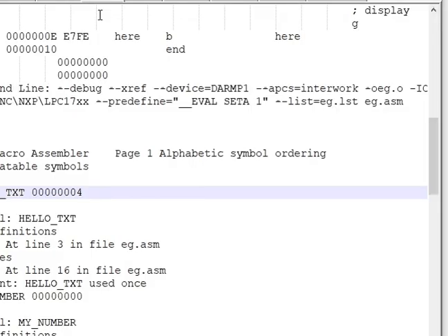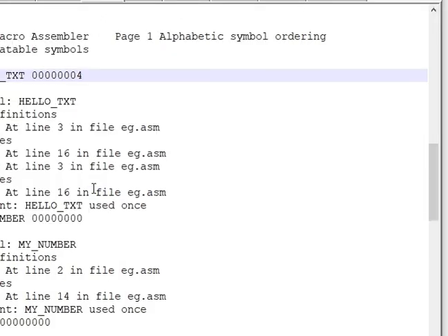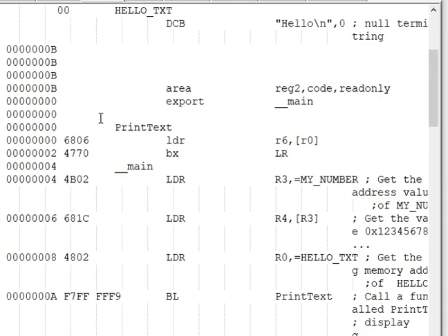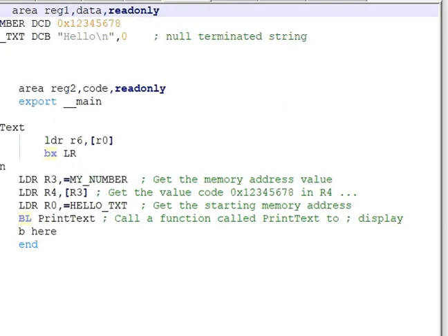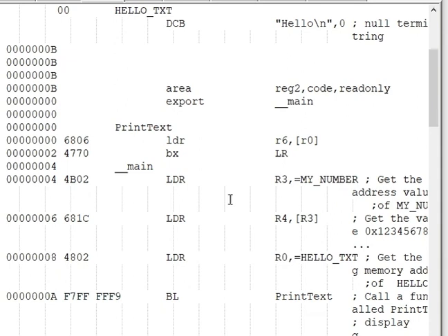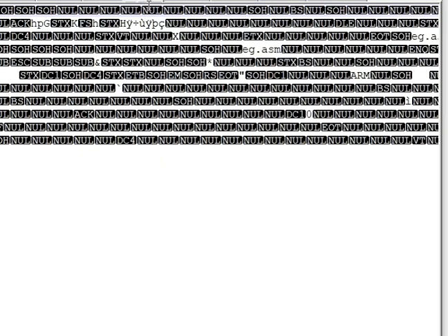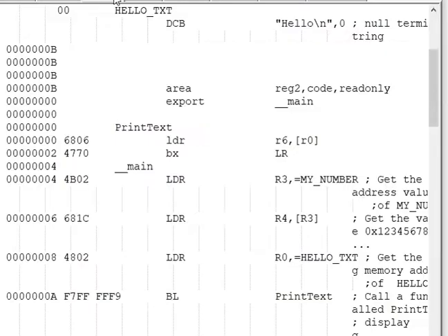This is your example.list file. When you observe it properly, it gives you the details about the address as well as the content, the mnemonic, and where this mnemonic is located, in which address. So all this information, which was not there when you look at your original source code, you can find in this file. And this .o object file would provide you some messages like assembling. So remember, whenever you assemble, you're going to get these two files.